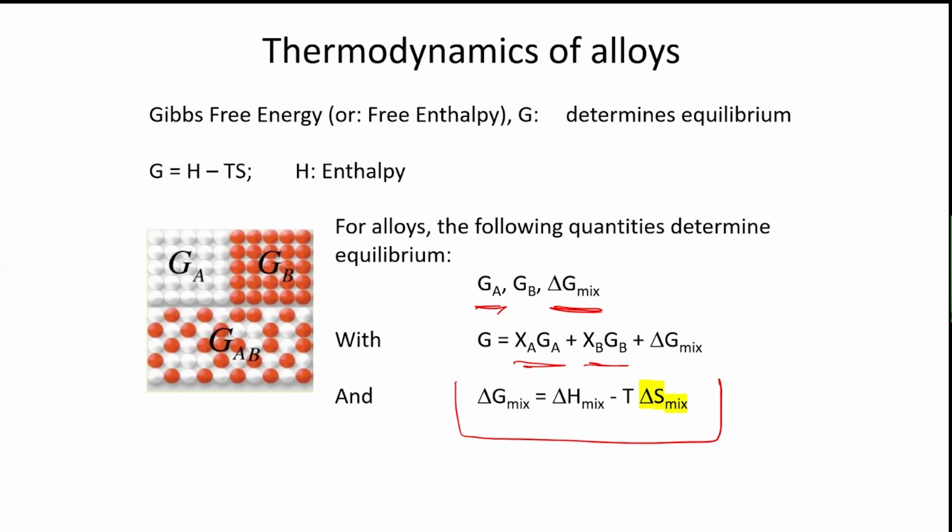So it means when we want to have a solid solution, then we need to have a high mixing entropy term, and it helps to have also a high temperature, so they should be high for having a solid solution, and this should be low.